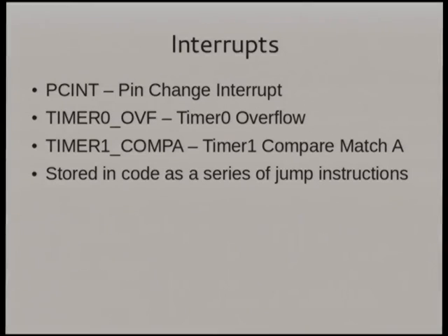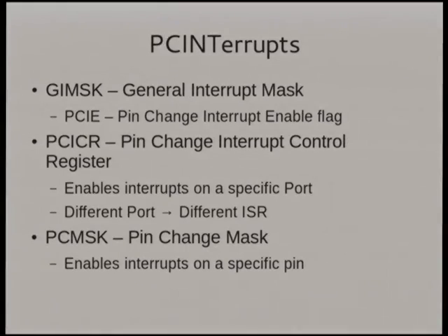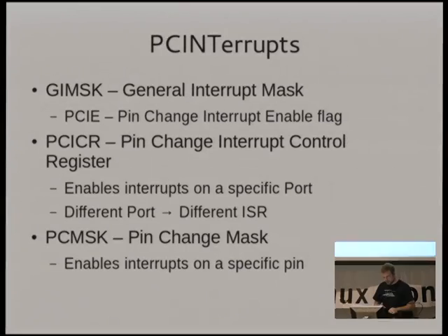The net upshot of that is, if you promise that you're never, ever, ever going to use interrupts, you can actually put your own code where the interrupt table goes and just use it as generic flash space. Probably not a great idea though.